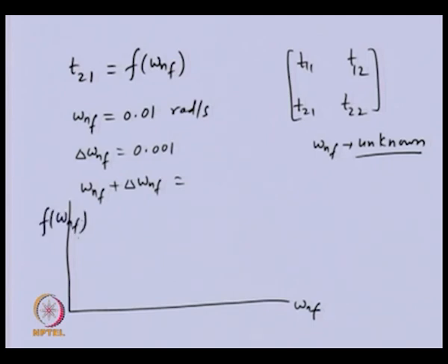because now you can see that when we assume some natural frequency, this overall transfer matrix we can get in numerical form, because all the point matrix and field matrix will be known to us, and we need to see just this particular T21 component for the example which we have shown.